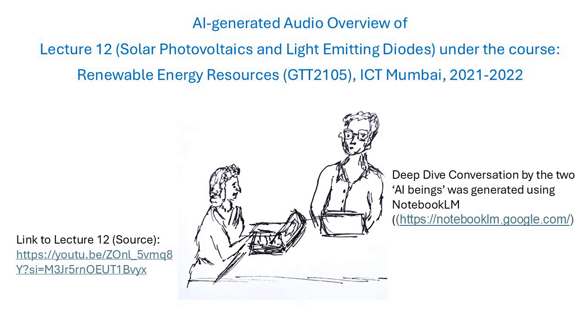We are. Now, to go beyond that 29% limit, researchers are developing multi-junction solar cells. Multi-junction, what's that? Think of them like sandwiches made of different semiconductor materials stacked on top of each other. Each layer is specifically designed to absorb a different part, a different color or wavelength range of the solar spectrum, more efficiently than silicon alone could. So capturing more of the available light energy. Exactly. By layering materials with different band gaps, you can convert more of the total sunlight energy into electricity. These multi-junction cells can reach much higher efficiencies, well over 40% in some lab cases.